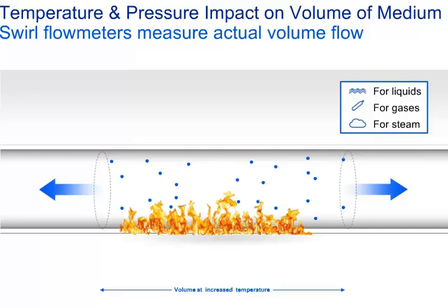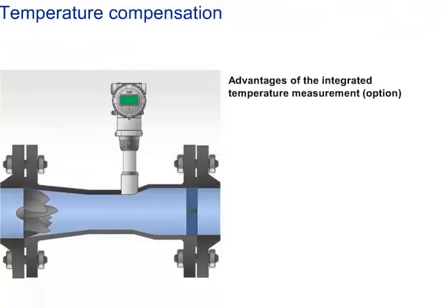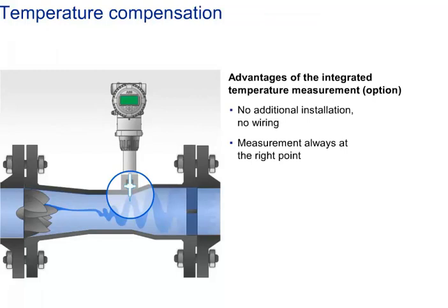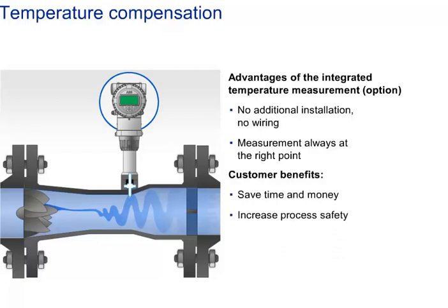For the compensation of the temperature effect, the temperature sensor, which is located directly in the piezoelectric flow sensor, can be used for this purpose. The customer can avoid measuring errors that may result from unfavorable PT100 installations or bad wiring, and does not have to spend time or money on a remote temperature system.